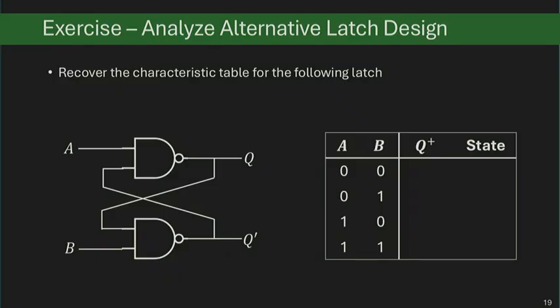Not necessarily. If you have a 0 at the NAND inputs, that directly sets the output to 1. So 0 and anything is a 0, you complement it, you get a 1. Some of these values are so powerful that you can do evaluation independent of the previous state. Yeah, I'd like to start with those cases first.